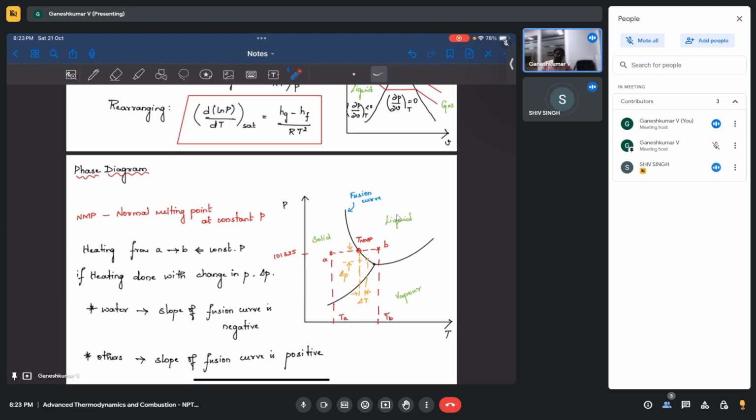Yeah, whatever you said is true. So basically any system can be defined by two states like P and T, right? When you define these P and T, you can define all the other things like energy, other things, right? But for the triple point, there is no such definition. It can happen only at one point. That's why it cannot have any degrees of freedom. Which means that at the triple point we know all the properties, including internal energy, entropy, every other property, temperature, pressure, the specific volume, everything we know, and it cannot change anymore.